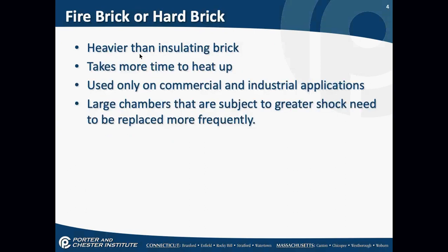Fire brick is a heavier material than insulating brick, okay? In other words, fire brick comes very close to the brick that you see on the outside of buildings. It takes more time to heat up. It's used only in commercial and industrial applications. They're large chambers, and the large chambers that are subject to greater shock need to be replaced frequently. Give me an example of where you might see a burner ignite with a lot of air pressure because of the shock involved in that burner ignition. Where might you see that?